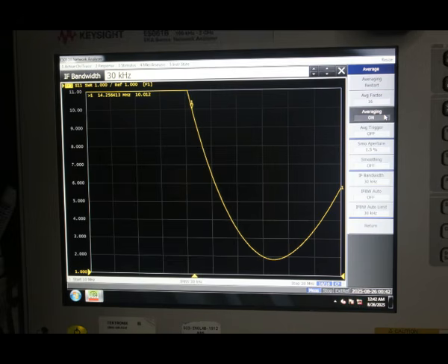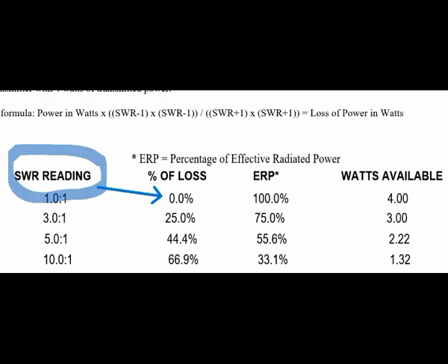And we're going to measure the power delivered into the dummy load in both cases with 50 watts applied at the transmitter end. I'm going to refer back once again to the tables that we can find on the internet or in books that try to relate a standing wave ratio at the load with a certain percentage of loss in a coaxial cable, and this is absolutely incorrect. This is not true at all for the cable loss due to a mismatched termination at the load.